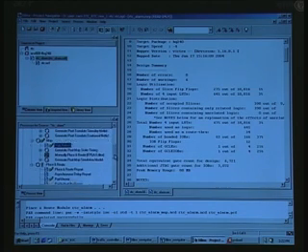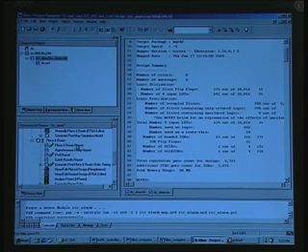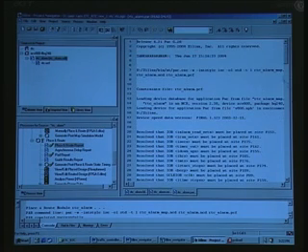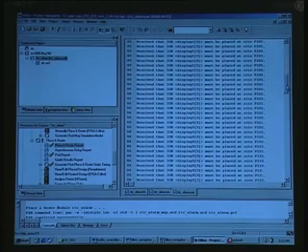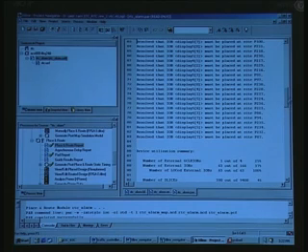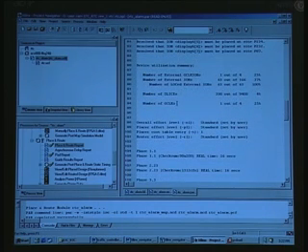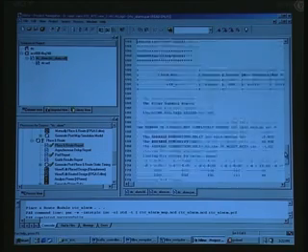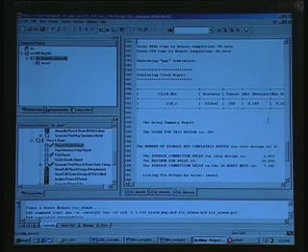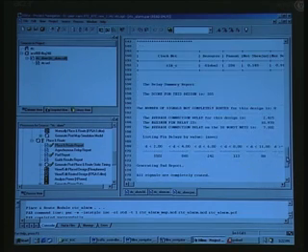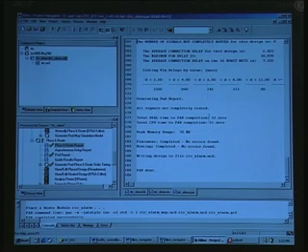And there is also a place and route report. You have once again a place and route report here, and it gives in more detail, for example which pin was connected to which point, and what IOBs are used, and all pin listing it is giving, and also what clocks are used, and once again number of slices used, and so on. And it also gives the timing summary here. Let us not go into the details right now. When we come to that design, we will see this, and basically the timing details, and finally it says place and route there are no errors, and that is what is here.